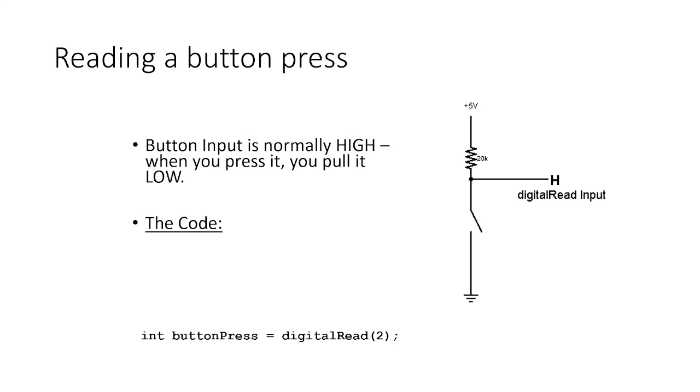So we have created, we said you can create a variable which will be used to store sensor data. Like for example, we can say our button is our sensor. So digitalRead will read the state of the button, then it will store it in the buttonState variable.